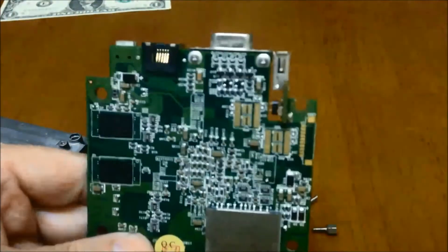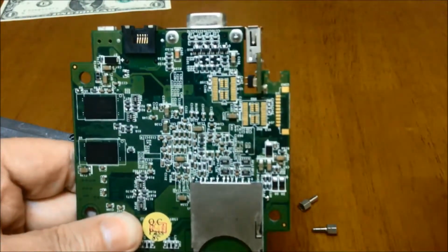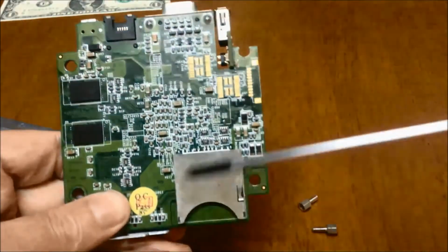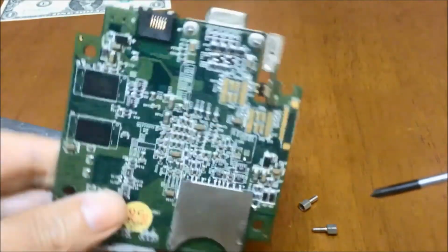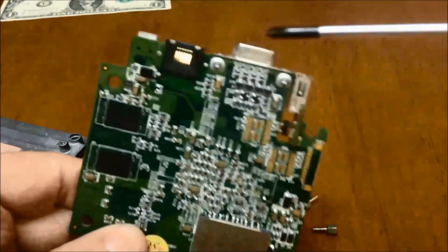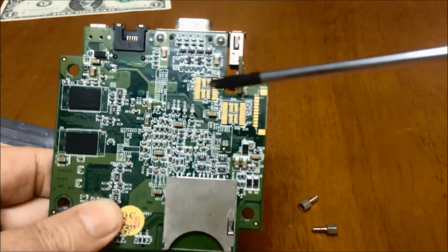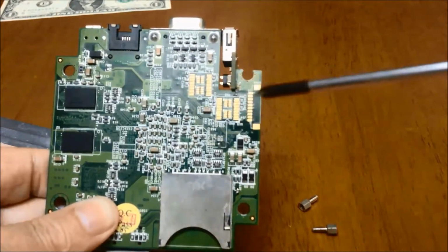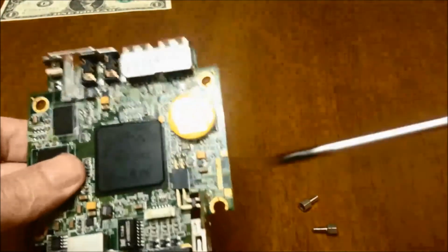And if we turn it over, you see there's very little on the back. 2 more DDR2 chips for primary memory, and of course the SD slot. You may have noticed that there's no serial ports actually coming out on the board, but if you look here, we've got pads on the board to put in the IC components and a header here to put in the actual DB9 connector, and the same on the other side.